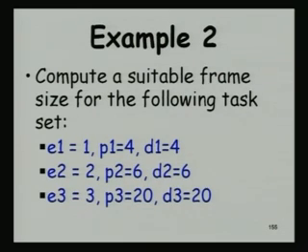In the previous example, you have said that we need to take 4 as the frame size. Yes, if we take 4, then the number of times the scheduler runs will be. Why only 4, why not 5 also? 5 is more than 4. So, what is the optimal case? No, see you can try 5 also, because 5 is also a factor of 20, but if 5 runs, for 5 also the tasks can run, then we can choose 5, that will also minimize the number of times it runs.